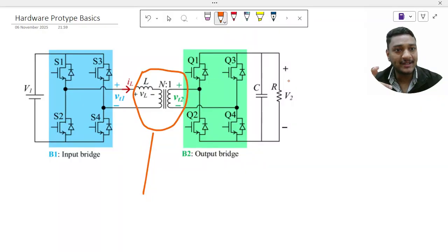Then we need the voltage sensors, okay? How to select voltage sensors, I have made one very basic video that is available on my YouTube channel, but I wanted to explain those things as well. There are really good points when selecting voltage sensors. Then we need to decide whether we need a current sensor or not, because only if you are going for closed loop do you need the voltage sensor as well as the current sensor. You can place the current sensor here and measure the current, if you are going for closed loop operation.